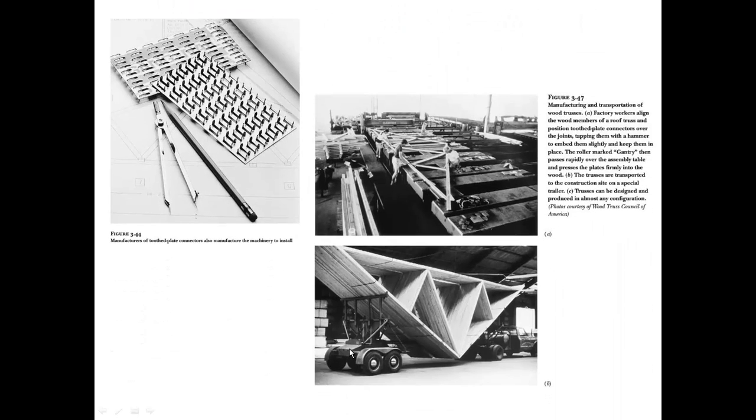Other types of fasteners that we see used on pre-engineered trusses, for instance, would be these toothed plates. This picture doesn't show them, but you'd actually have tooth plates at all these joints holding the wood structures together. We see a lot of pre-engineered wood trusses being manufactured. They're quicker, easier, and less stress getting them up in place. So it's just less liability, I guess, if you're using pre-engineered trusses.